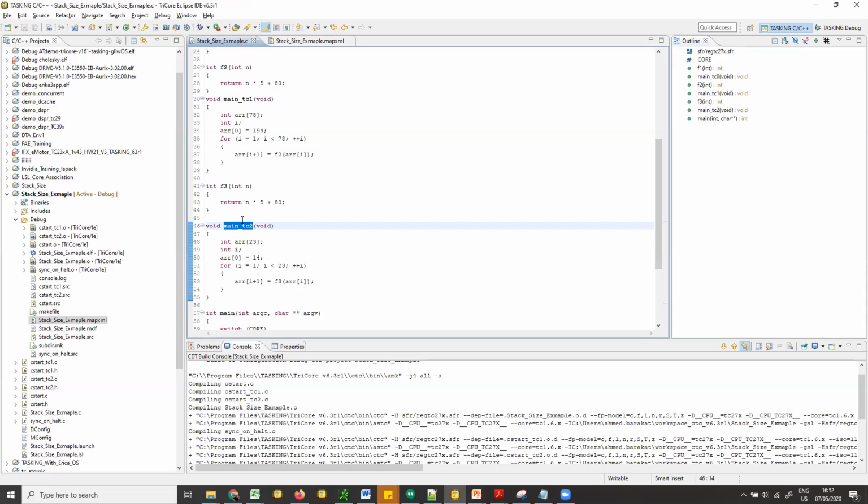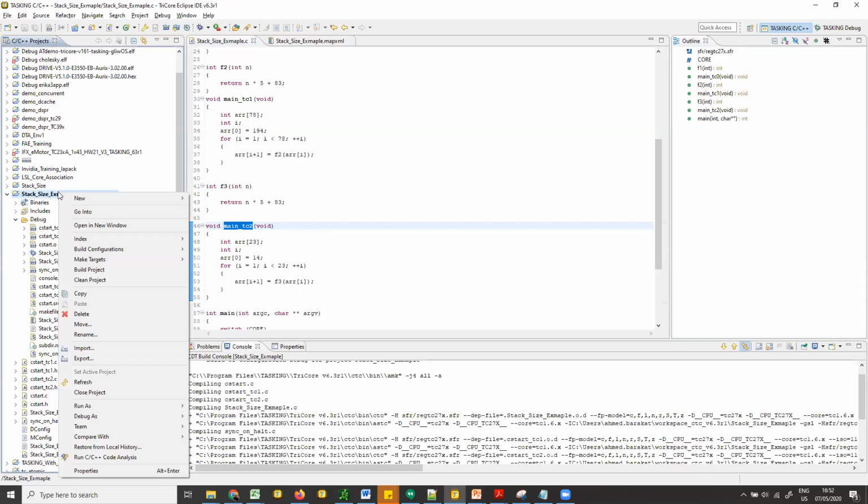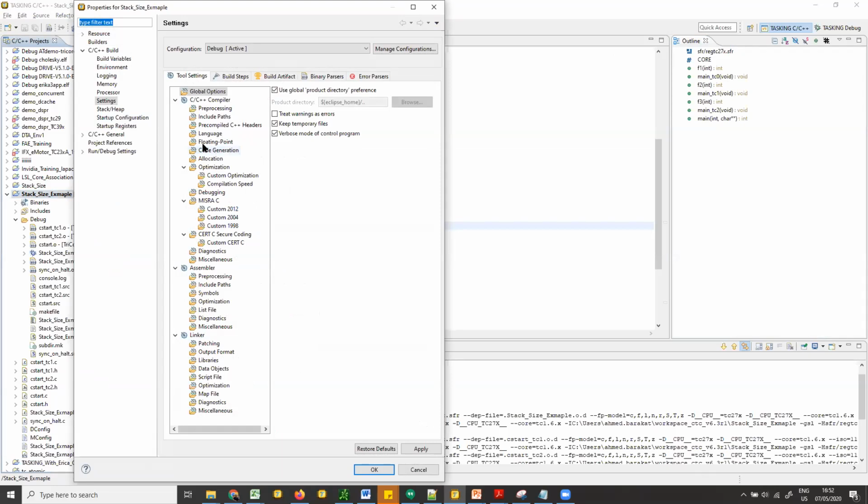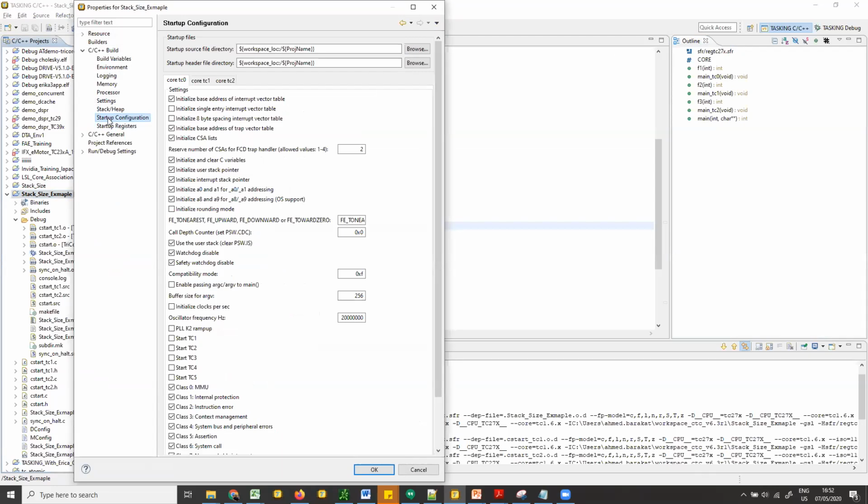So how could I do this? You could do this by first letting core number 0 enable core number 1 and core number 2, using the startup configuration. If you go to the startup configuration again, and click here on Start TriCore 1, and here on Start TriCore 2, that means TriCore 0 will start TriCore 1 and TriCore 2.